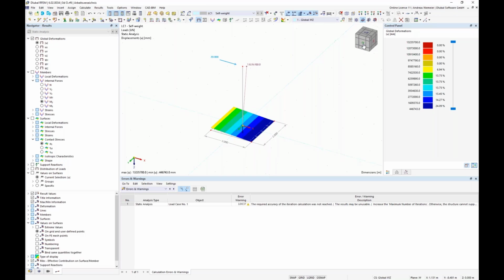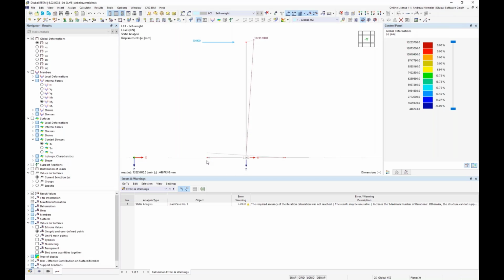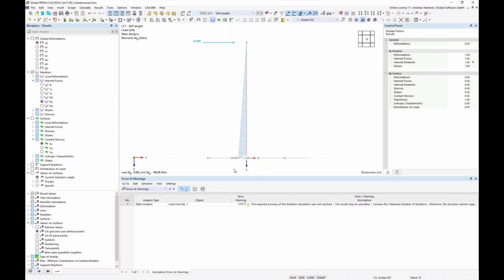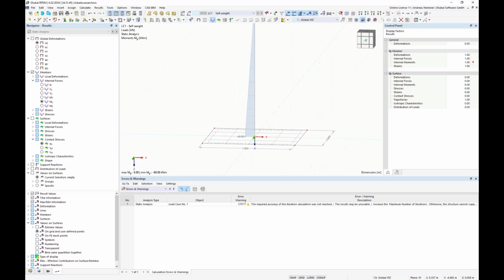And when we check the, let's say, deflection shape from the last situation, you see we have here an uplifting situation. This slab or the full construction is not able to transport this bending moment down to the bottom because it's too slender. The weight is not enough. And now the question appears, what can we do? We can reduce the load, or we can modify the size of the slab. For today's session, I want to do both. Let's do the easier one at first.